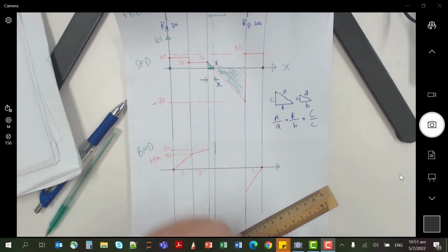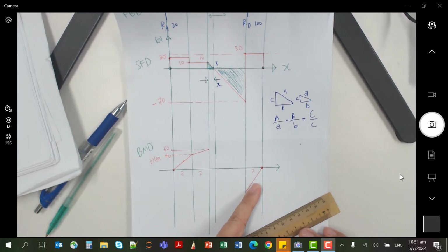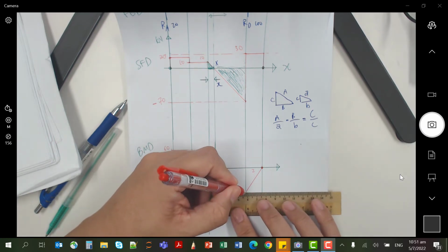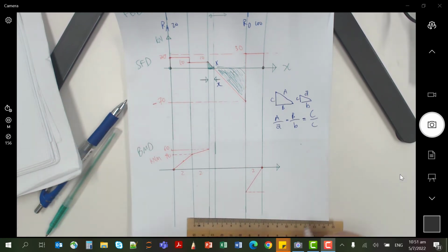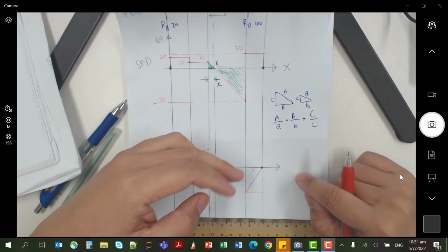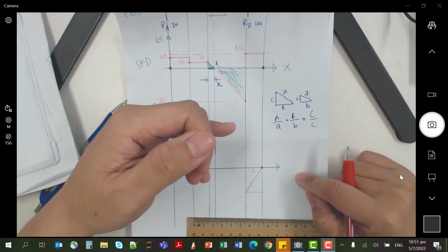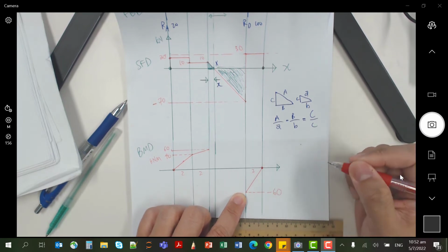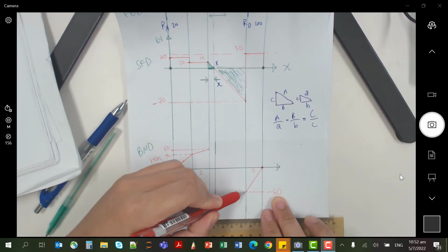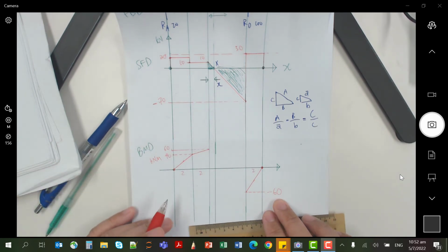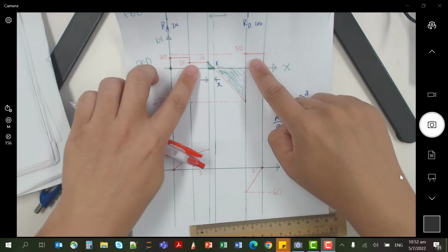So it should be around this, sloping up, gradient 30 and at 0. That's the scenario. So what is this value here? Again, it is 2 meters, and it is climbing 30 for every 1 meter. So I should start from minus 60 over here. Minus 60. After 1 meter, I reach minus 30. After 1 meter, I reach 0. So we are done with the constant gradient portion.